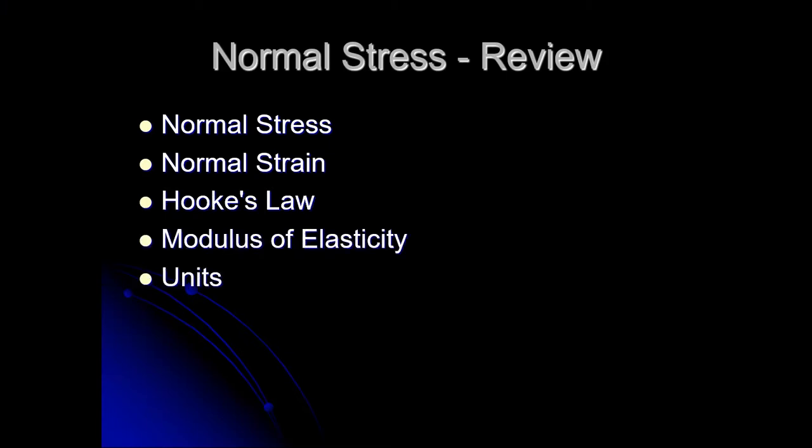I do have to say a word on units here. You have to stay consistent between the units that you use for stresses and for Young's modulus. If you're using stresses in KSI, then you have to have your Young's modulus in KSI also. Otherwise, you end up being off by a factor of 1,000 or maybe even a factor of 1,000,000. If you use stresses in PSI, then your Young's modulus has to be in PSI also. You have to keep consistent with it.